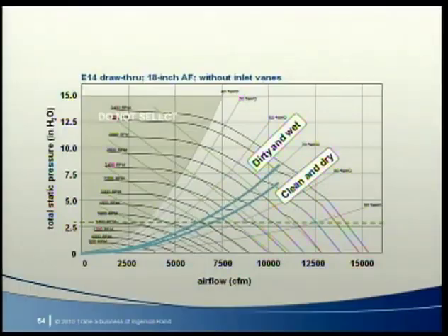Of course, the highest pressure drop path could be through any zone, so if it's not obvious, we should really calculate pressure drop for each path at design conditions and use the highest value. Since the pressure for this system is pretty high, we'll try an 18-inch airfoil fan. As with any fan, this one has a selection envelope. The fan must operate within this envelope at all conditions.